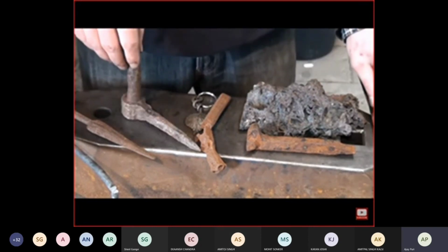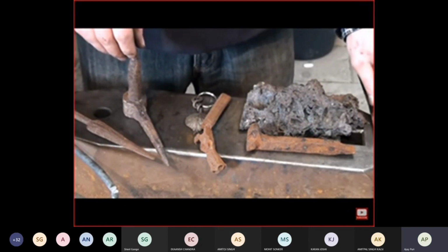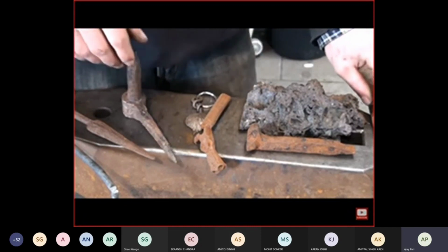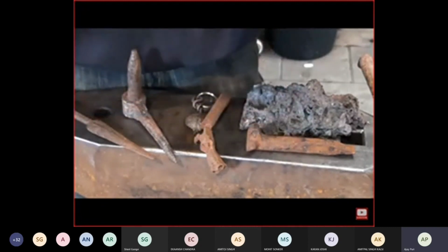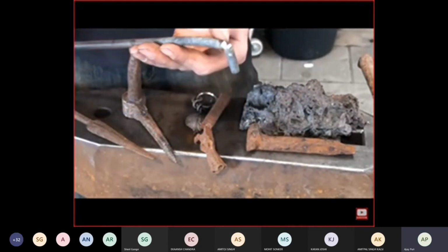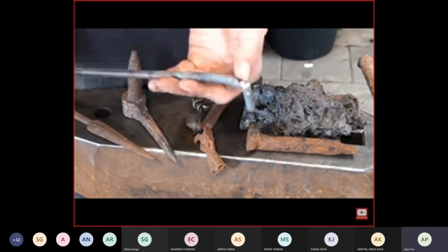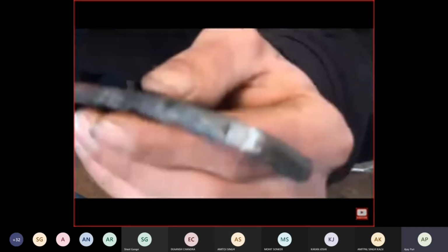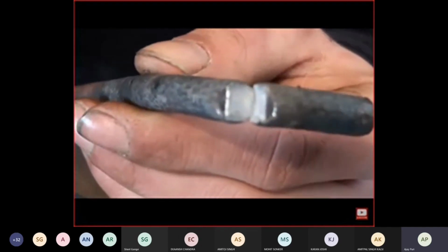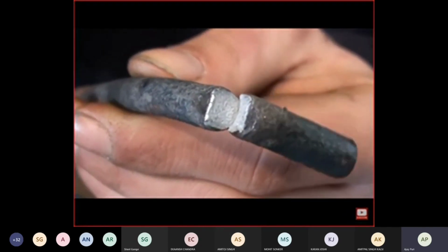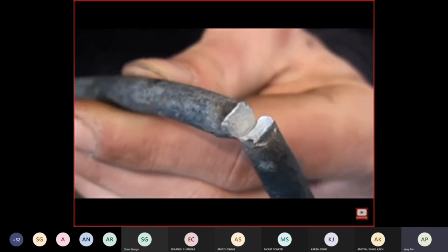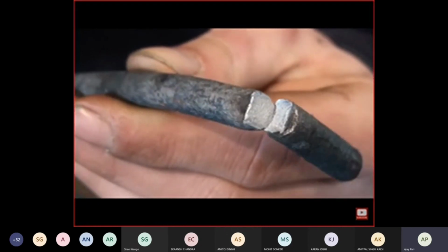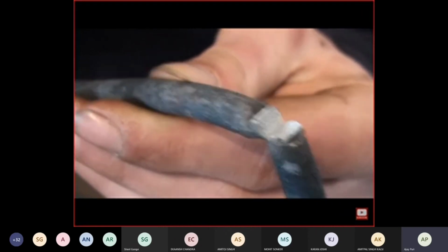It's totally different. Apart from rusting, you can also have a closer look at what the material does when you break it, because that is very different from mild steel. I got a bit of mild steel bar here, and I've done a nick and break test right at the end here, so you can look on the inside at what that structure looks like, and it's very different from wrought iron. If I bring that close, you can see it's a bit like taffy, very consistent and not very particular. This is just mild steel bar.